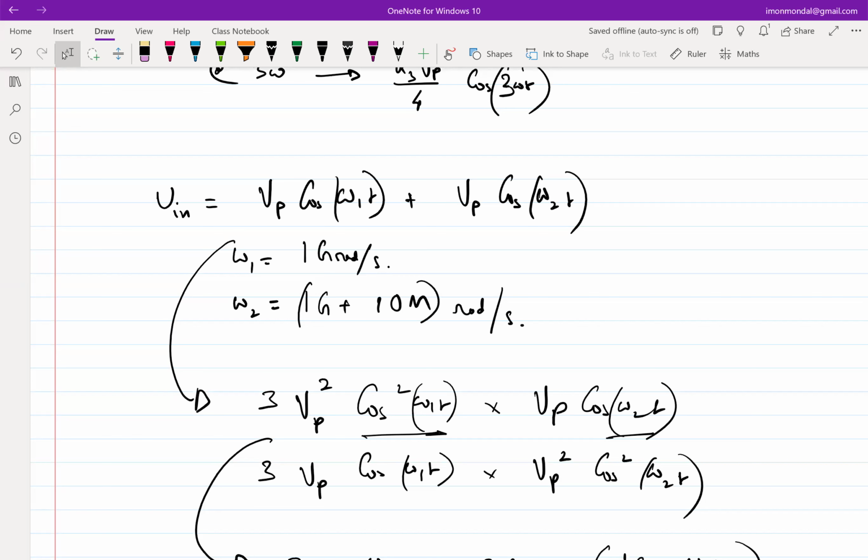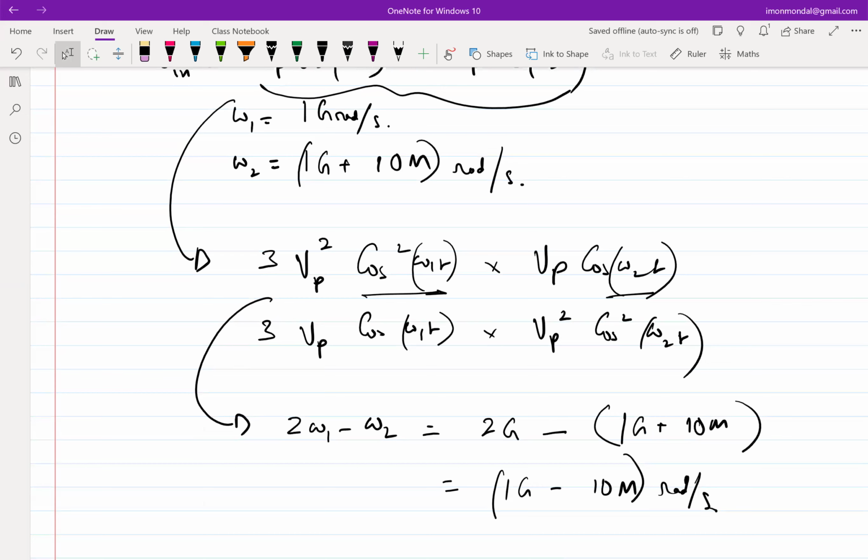Now you're up converting them around 1 gigahertz and you're sending it out through your power amplifier. So now your power amplifier is distorted, right? Or when you are receiving a signal, your LNA is distorted. When you are receiving these pristine signals, let's say internet signals, and you pass them through a distorted device, you are going to generate these additional tones.